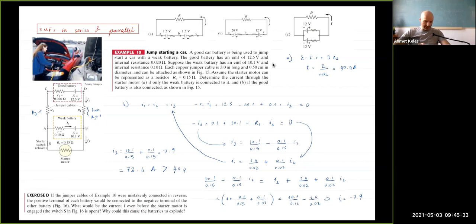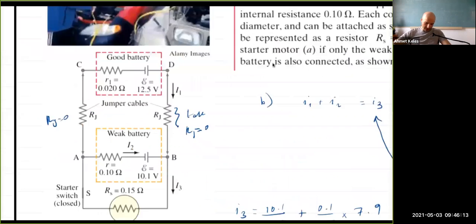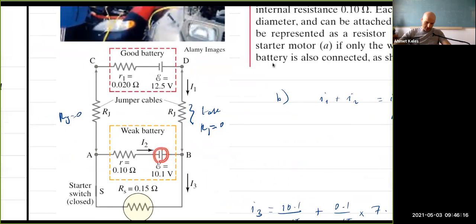Right? What happens if you connect this side to this side and this side to this side? And forget about this. Let's say you didn't start your engine, you just connected the batteries. And what do you expect? So I think what happens is, maybe I can show you here. This battery will be reversed, or you can think of this battery being reversed. Then there is a battery like this. This guy comes in, and there is another battery like that that's also in series. You have twice as many volts as you would have, and almost twice as much current.